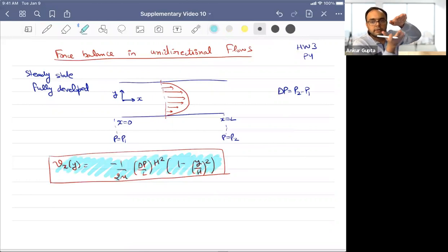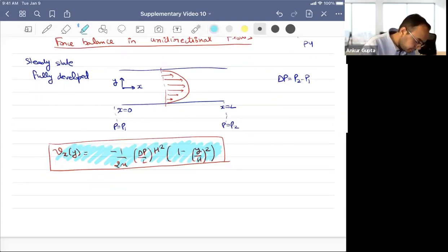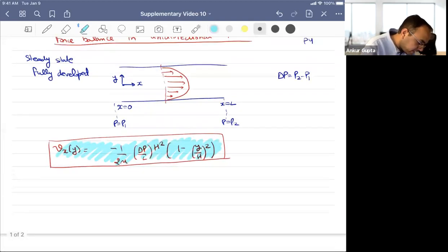Now that we have discussed this, I hope you can imagine that if the plates are at rest and the fluid is moving, the fluid is trying to drag the plate with it, right? So it is applying force on the plates, and of course the plate is applying the equal and opposite reaction on the fluid. We have discussed stresses, and we have also discussed forces in a hydrostatic system. But what I wanted to do was a force calculation on a system with flow. In hydrostatics we have done that, but we have not done that with flow. So the goal here is to actually construct a